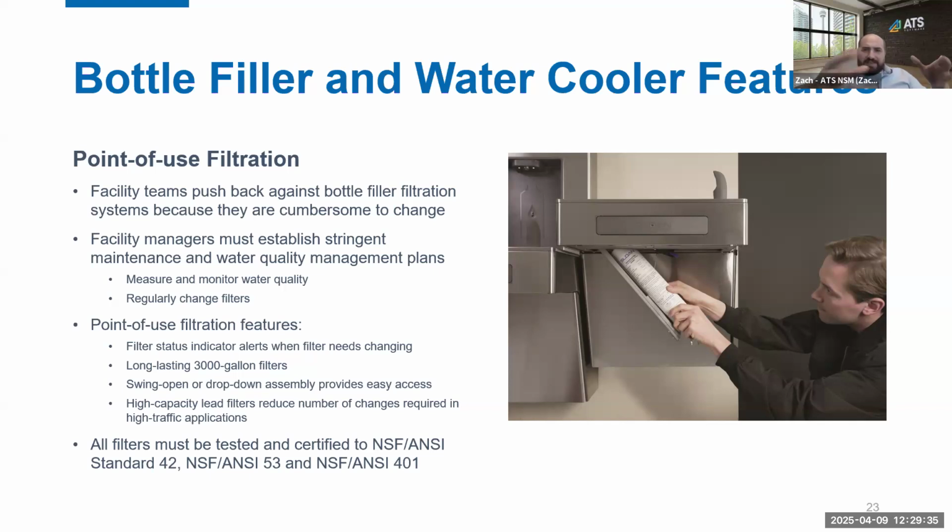I always thought you had to take the entire thing off in order to. Yeah, so that's how the original design of many of the brands out there were. You would have to lie on your back, take out the 4 screws and take the entire skirt off to access the filter, which was jammed in very tightly within that cooler space. Some of the newer design models that you're seeing in the picture there have this quick access drop-down door, so you could change your filter in under a minute, which is a very nice feature to have.